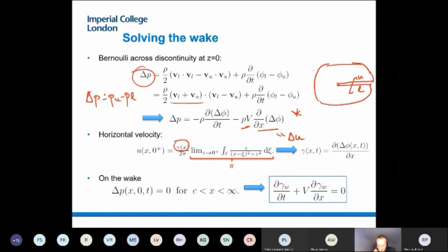So in that case, that can be very easily seen by doing a bit of algebra on the potential flow equations, that the velocity is equal to half of the value of the local circulation. When you look at the jump of velocities, that becomes twice the jump. So that basically links the local distribution of circulation, of vorticity gamma, to the jump of the horizontal component of the velocity, which we write in terms of the derivative of the velocity potential in terms of x.